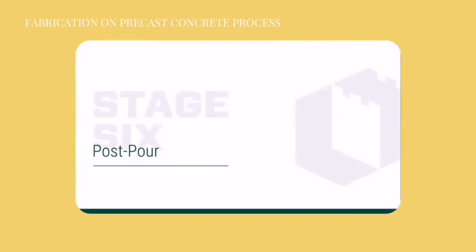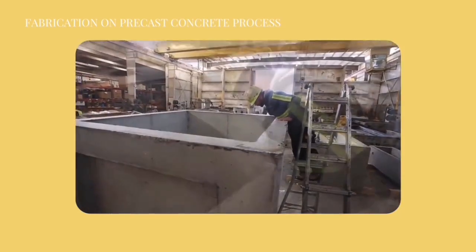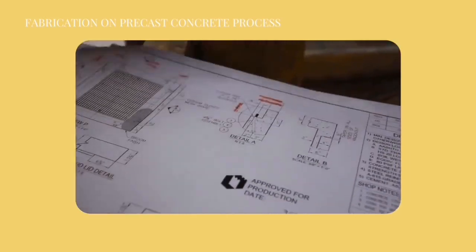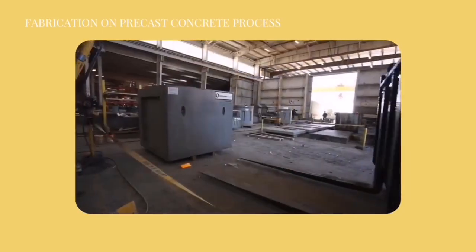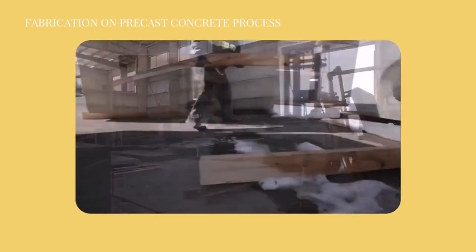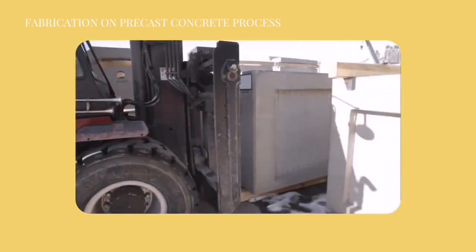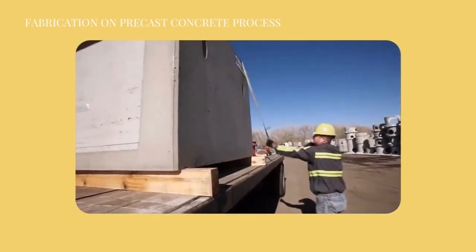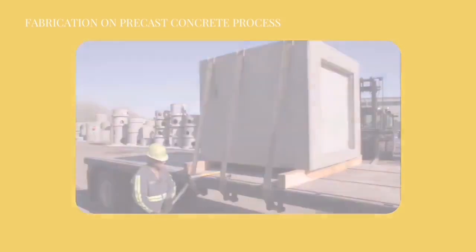Once the product has been removed, it is then cleaned and the post-pour inspection is conducted. If all design dimensions have been maintained and no visual defects are noted, the QC technician will sign off. The final product is then labeled and transported to the yard. Care is taken to make sure it is stored on proper dunnage as it awaits the customer demand. When the customer is ready to receive the order, the product is loaded on a truck and properly tied down for shipment and delivery to the project site.